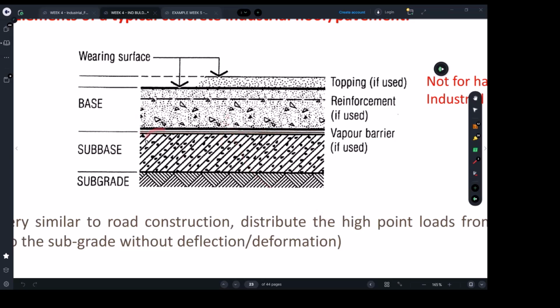There is a sub base. The sub base is the topping we put, and we make sure it's well compacted, just in case the subgrade was rough. We can't have it rough, because maybe in some parts you've got rock, sometimes a bit of sand, some places a bit of clay, and that will end up having uneven distribution of loads, which will compromise what we're trying to do.